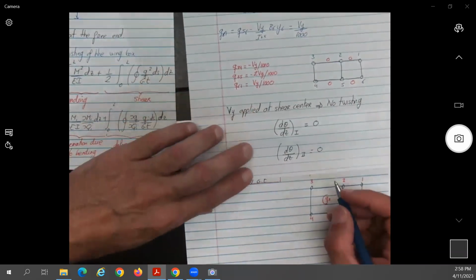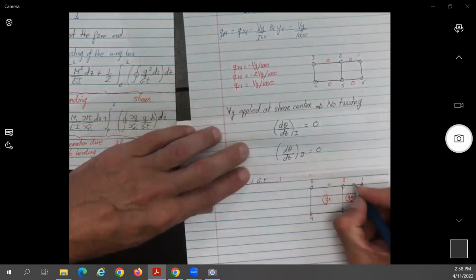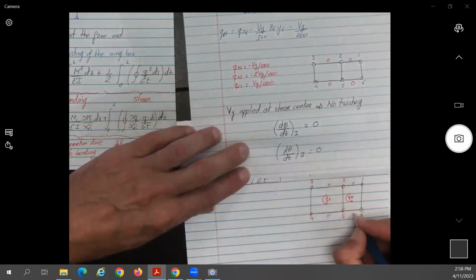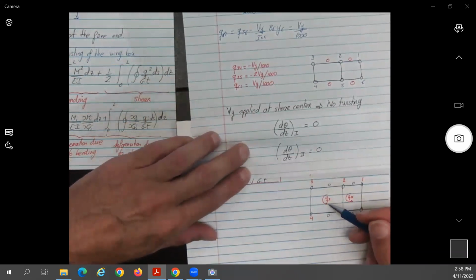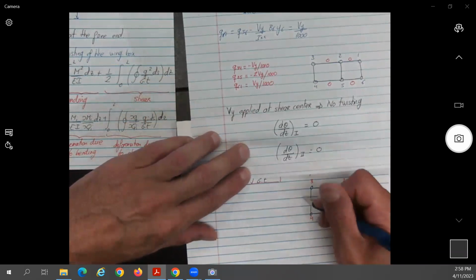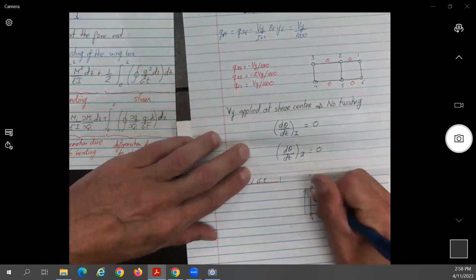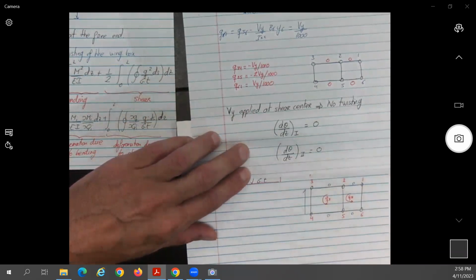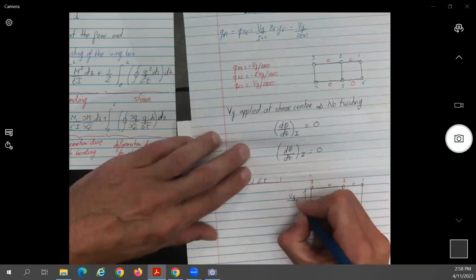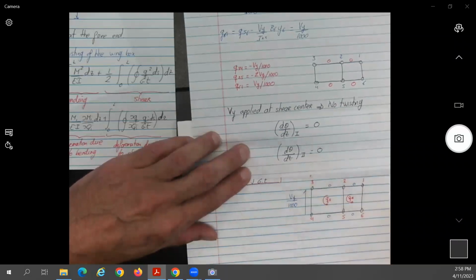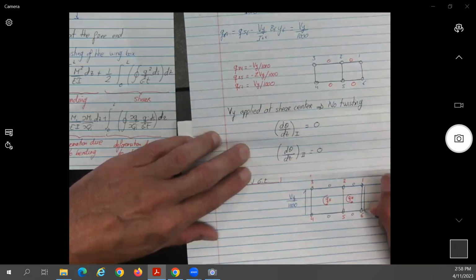So we know here the shear is 0 over here on top, 0 over here, 0 over here, and 0 over here. But we need to find out what is on the side. So Q34 was equal to what? Negative, no? So we know that it should go actually, instead of going down, it should be going up, no? Yeah. And the magnitude will be Vy over 1000. Q61 is positive, so we can leave this one positive.